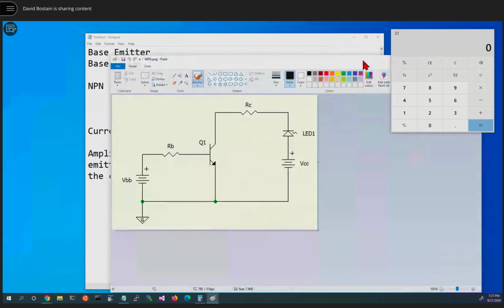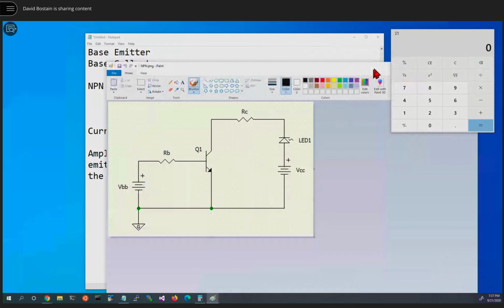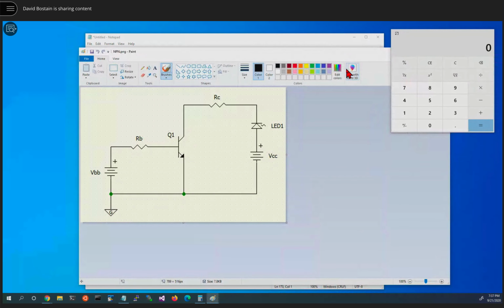Okay, here's a circuit using a transistor. And believe it or not, we're smart enough to actually work this already, but we need to go through an example. Notice I took the circle off that would normally be drawn around the transistor, because sometimes in the symbol the circle is missing. It's not necessary. It's labeled Q1. Notice in this circuit, I have two batteries. One that controls the collector side, VCC, and one that controls the base side, called VBB.